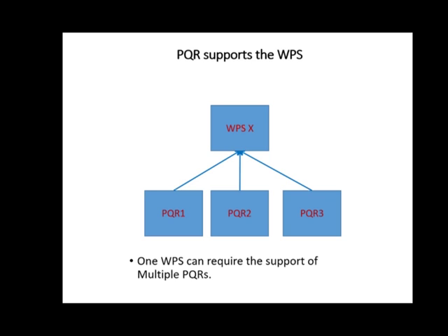And instead of going and qualifying a procedure that does all of those, maybe I've got procedure qualification records laying around that contain all that data. So I go and find the appropriate PQRs, I gather them up, 1, 2, and 3. Yep, this one covers my gas tungsten, this one covers my shielded metal arc, and this one covers my submerged arc welding. So I put all 3 of those together, I write a WPS, I reference those 3 PQRs, and now I've got a WPS that is supported by 3 separate PQRs. And this can also pertain to post-weld heat treat or any number of essential variables. But a lot of times you'll look at a WPS and you're trying to do some work and not all the essential variables are addressed, so you have to go back and look at the other work and see what you can find.